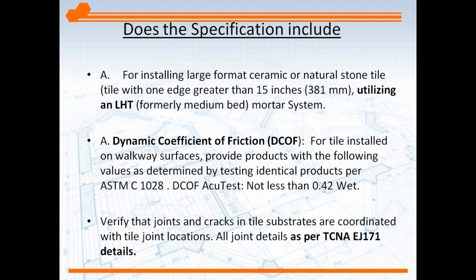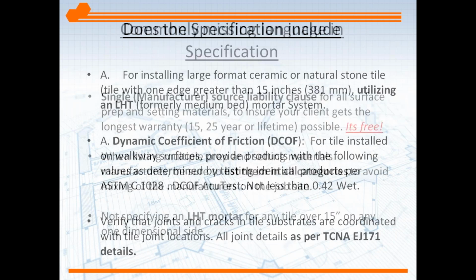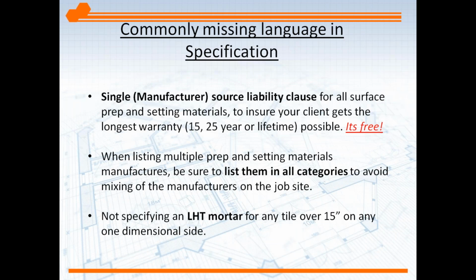Verify that the joints and the substrates are coordinated with the tile joint location. Again, some joints cannot be moved. You see the one in the concrete, it can't be moved. So when designing, as hard as it is, you need to take that into account when you're designing your pattern in the floor.